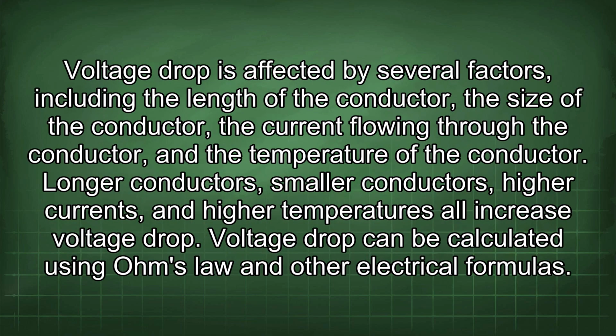Voltage drop is affected by several factors, including the length of the conductor, the size of the conductor, the current flowing through the conductor, and the temperature of the conductor. Longer conductors, smaller conductors, higher currents, and higher temperatures all increase voltage drop.